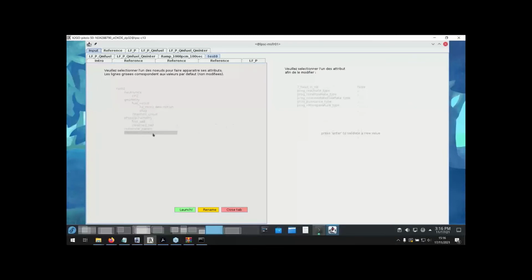You go to transient here, and you set up the reactivity. You say I would like a transient starting at 10 seconds, and I would like to go from 0 to 1000 in 100 seconds. No, in 1 second, something faster.